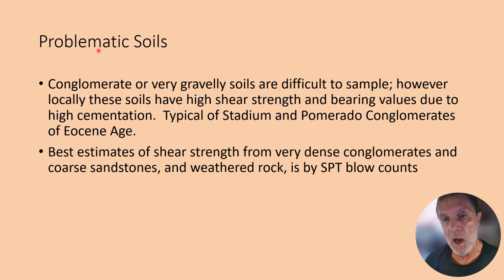In the past, we got a lot of Eocene conglomerates. And then through time, of course, these gravel bars or channel deposits became consolidated and cemented, and they're very, very tough and strong. They're extremely difficult to drill through. You can chip away at it, but trust me, these have high shear strength and high bearing values.